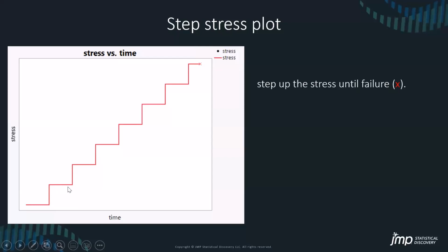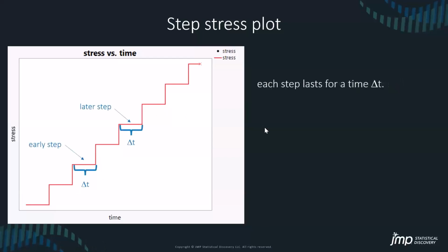All we're going to really care about is how long it was at this particular stress, and how long it was at this stress. Only the flat part of the stairs, not the vertical part. And so, we're running our test, and we ramp and we ramp and we go up, up, up until finally we get a failure. Okay, that's the idea. We're going to get failures by this ramp.